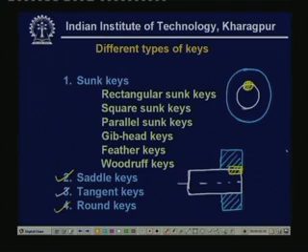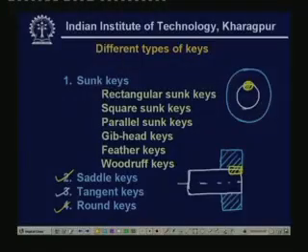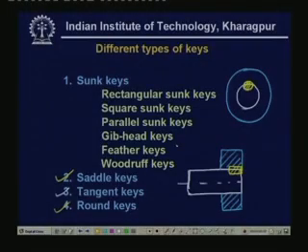Now, what is the advantage of the round key? The main advantage is that it is drilled after the final assembly. So, we can take this advantage that the alignment can be done properly. Also, it can withstand quite a high amount of load. So, the capacity is quite large as well as the alignment could be fairly acceptable. Now, these are the different types of keys.